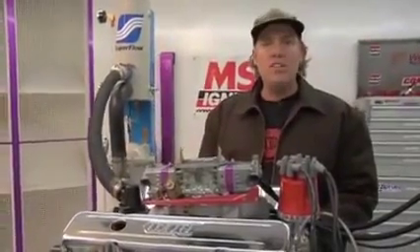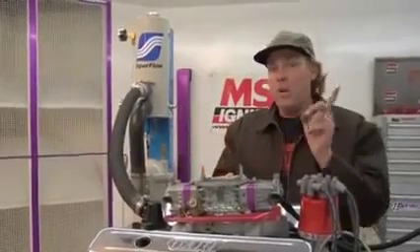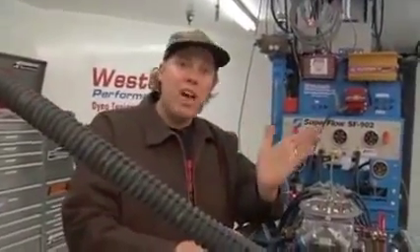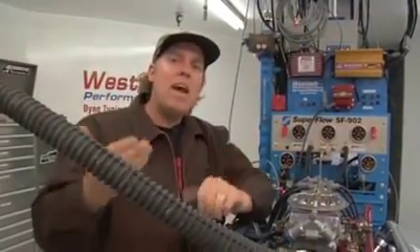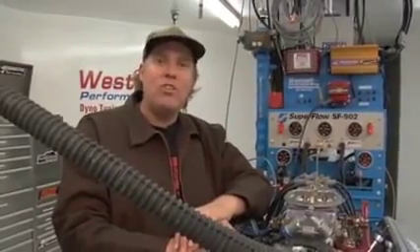The third thing you need to know is ignition timing curve, which is the rate at which the ignition timing advances between the initial timing and the total timing. Now I've explained that there's an ignition timing curve between initial timing, which is a lower number, and total timing, which is a higher number. But you might ask, why does ignition timing need to advance as engine speed increases?